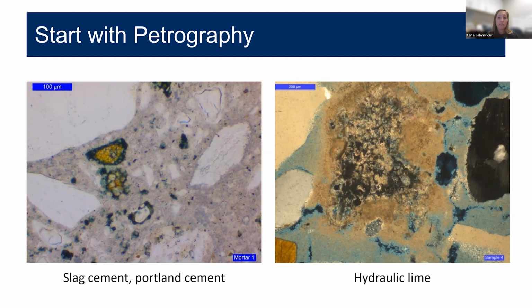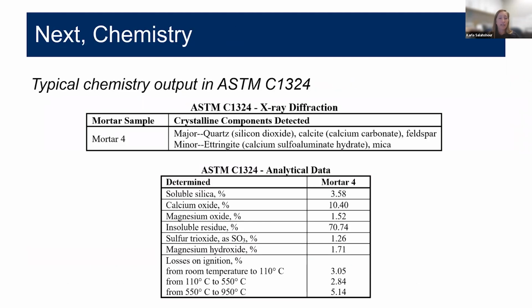We also look for leaching that may have occurred from the paste, say during exposure to moisture and moisture migration through joints over time. And we look for the general competency of the fragment. Is it hard? Is it soft? Does it fall apart and crumble? Once we make those petrographic examinations, we start our chemical testing.